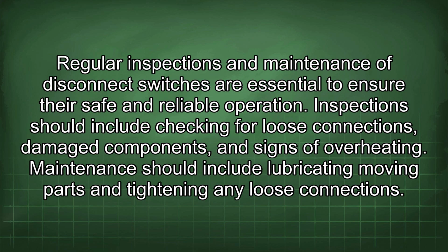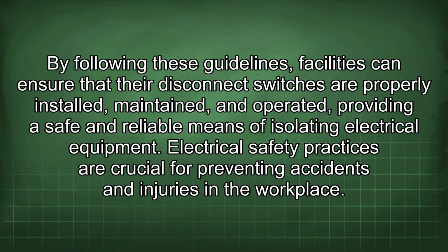Regular inspections and maintenance of disconnect switches are essential to ensure their safe and reliable operation. Inspections should include checking for loose connections, damaged components, and signs of overheating. Maintenance should include lubricating moving parts and tightening any loose connections. By following these guidelines, facilities can ensure that their disconnect switches are properly installed, maintained, and operated, providing a safe and reliable means of isolating electrical equipment.